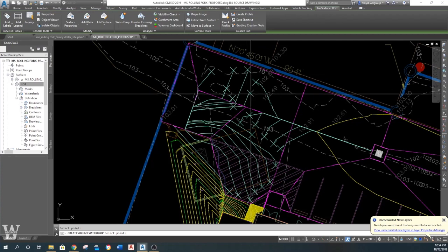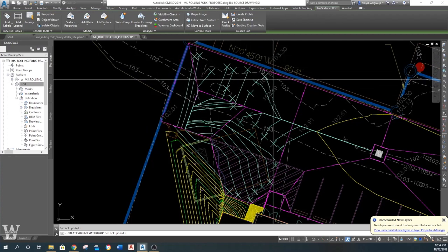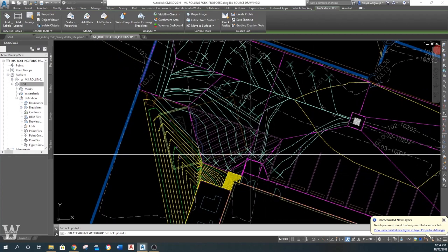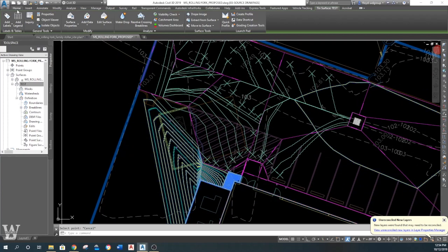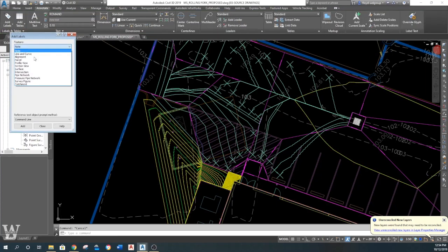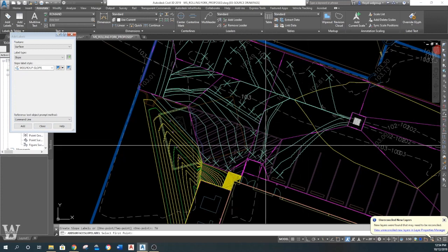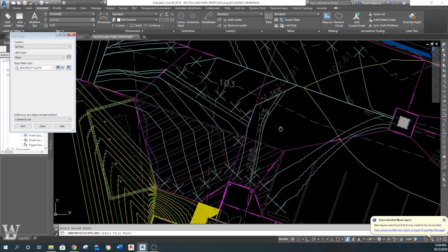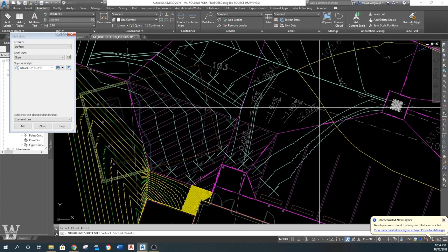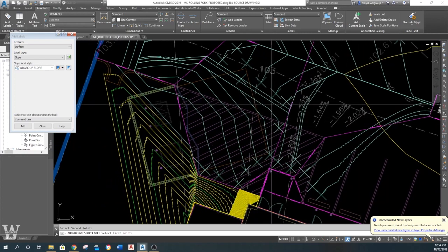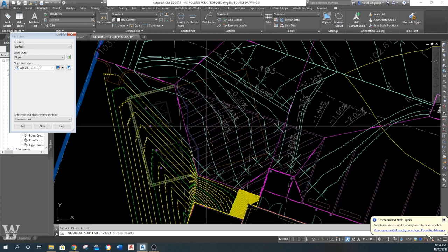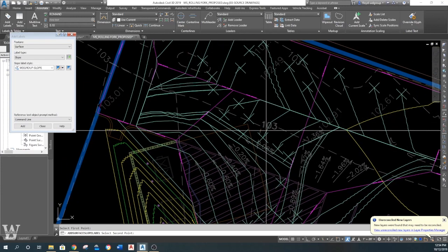Okay. And what's nice with the start points, it gives you a place to see where everything breaks. Okay, so now we're going to annotate, add label, go back to surface slope, tell it what surface 2 point. We still got what we had a while ago there, but now our elevations are better. Further we get away, the better. What do we look like? We're still flat. Okay, the water's going that way, but it's flat when we get over here.